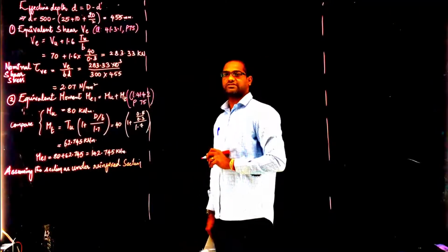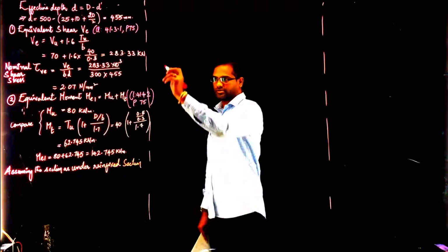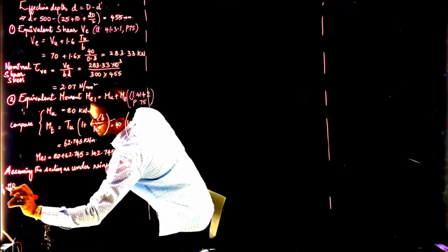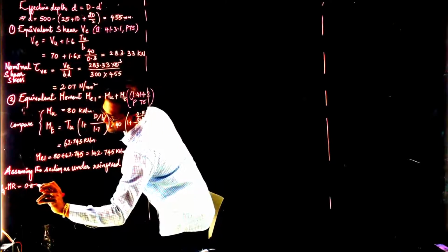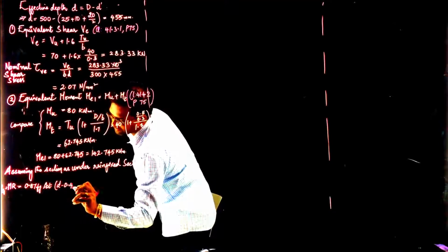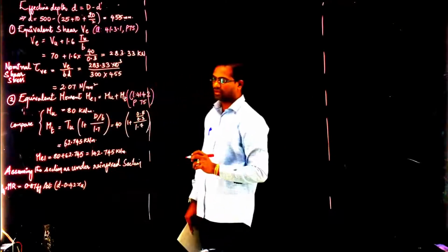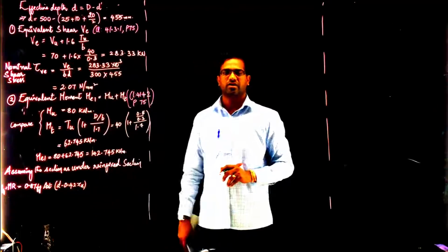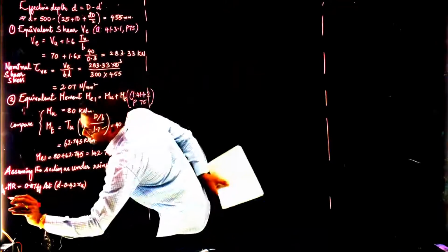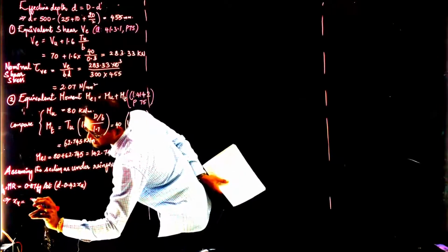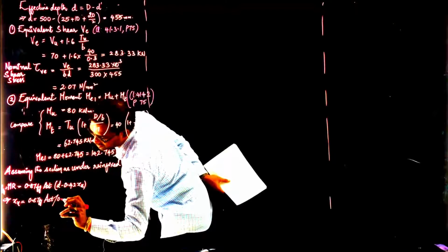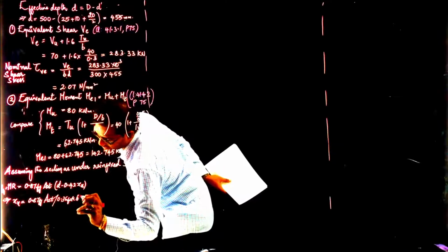now equating moment of resistance with ultimate moment which is coming MU1, then MU1 equals MR equals 0.87 fy AST into d minus 0.42 xu. Right? There is also another equation which is in the code, that is equation 4 of the annex. So in this, xu is given by 0.87 fy AST divided by 0.36 fck b.